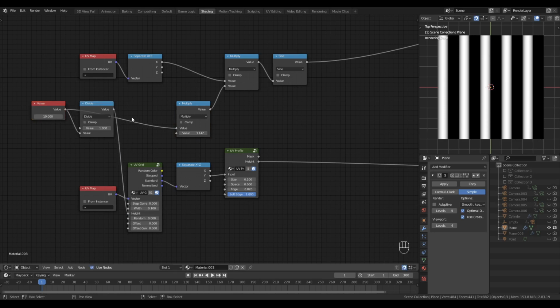As you can see, things have got a little messy and turned around, and I've had to move nodes in all sorts of directions. Now I can do this a different way. For example, here I decided to provide the number of instances that I want, and that goes straight to the sine function, whereas I had to transform that number before providing it to my UV grid. I had to transform it into tile sizes, essentially. I could do it the other way. I could input tile size here and then transform the value that gets sent to the sine function. This is just an example of how we can move fewer nodes around to take better advantage of the space available to us in any given network. Nothing more than that.